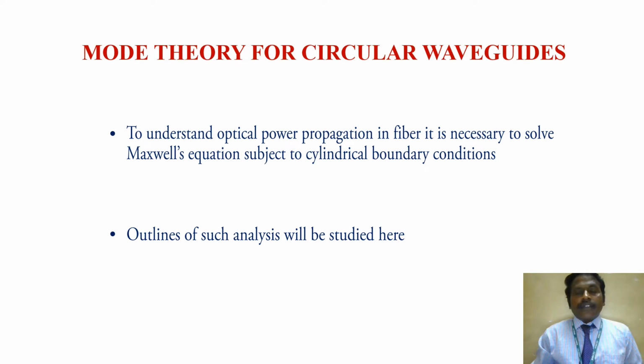Then the mode theory for circular waveguide. Under this heading, we are going to talk about power propagation in a fiber. It is necessary to solve Maxwell's equations subject to the cylindrical boundary condition. To understand the optical power propagation in the fiber, we need to know the solution of Maxwell's equations under the cylindrical boundary condition. The outline of such analysis will be studied here based on the equations.